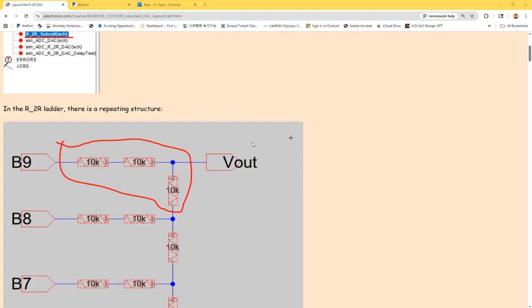You can see this resistor string has so many components. In the future, any of these VLSI design experiments or projects, all of these are doing modular design. You can see this one, we can put these three resistors into one module and save it as a cell. In the future, when you assemble another schematic of this R2R ladder, even though it's a really simple example, not any sophisticated VLSI circuit, it's still reducing a little bit of the hassle and workload. So what you do is grab this one and build a module out of it.